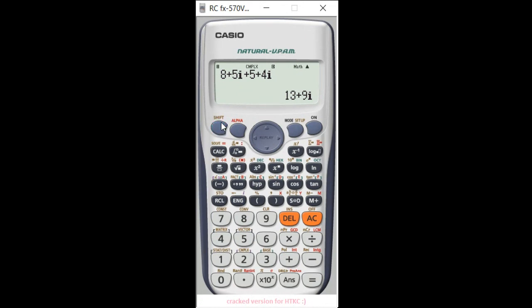You're going to convert that into the phasor form or the polar form. You go shift 2, complex 3, equal, boom, and you get it. Let's go back, just click answer. Shift 2, 3 and equal. I'm just pressing that button with the S to D, which basically gets you from a fraction form into a normal decimal number. So that's 15.81 at an angle of 34.69.